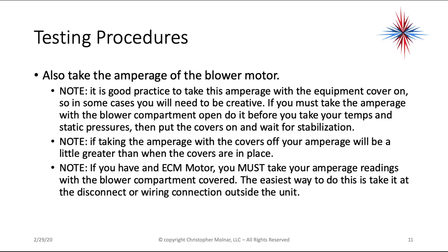If taking the amperage with the covers off, your amperage will be a little greater than when the covers are in place. If you have an ECM motor, you must take your amperage readings with the blower compartment covered. The easiest way to do this is to take it at the disconnect or wiring connection outside the unit. With an ECM motor, you cannot achieve proper amperage, rotation, and speed unless the motor is running at its normal condition, and that's with the covers on.